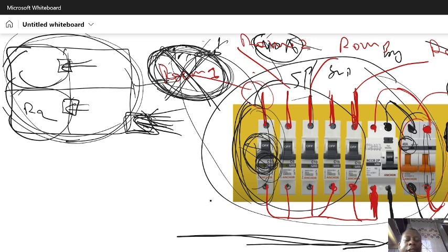Now the same thing for this room. This room we have C6, 6 ampere. We should not exceed this rating of this circuit breaker, same as all other rooms. Now let's say for example we have 40 ampere here. Remember, the 40 ampere here has to be the summation of this one plus this one, this one, this one, and this one.